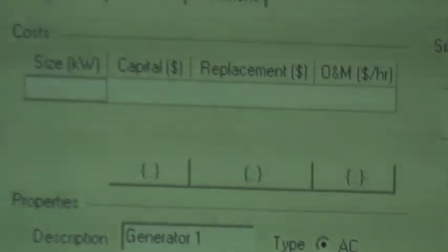If it's a new site, then I would definitely recommend a smaller diesel generator. Instead of 20 or 30 kVAs, maybe you can go for 8 kVAs or 10 kVAs, whichever comes easy for you.